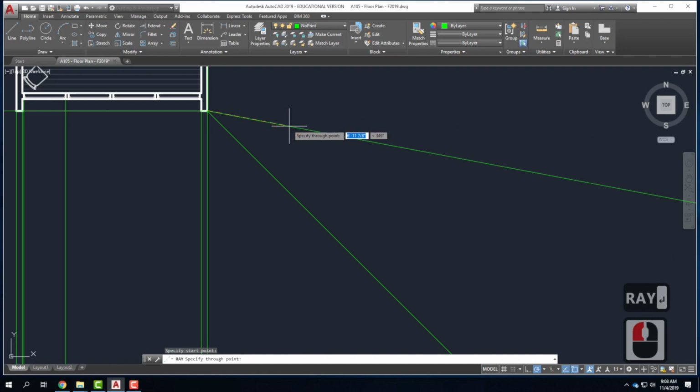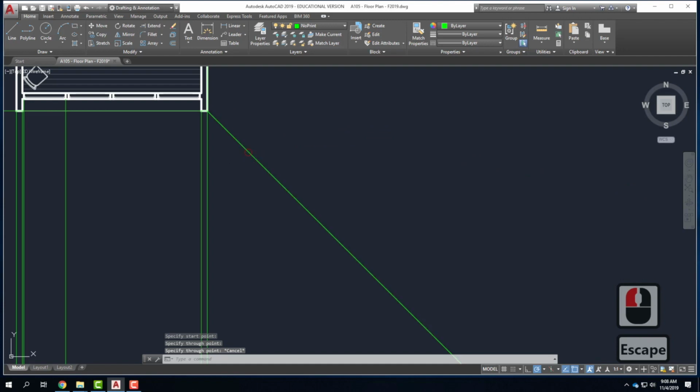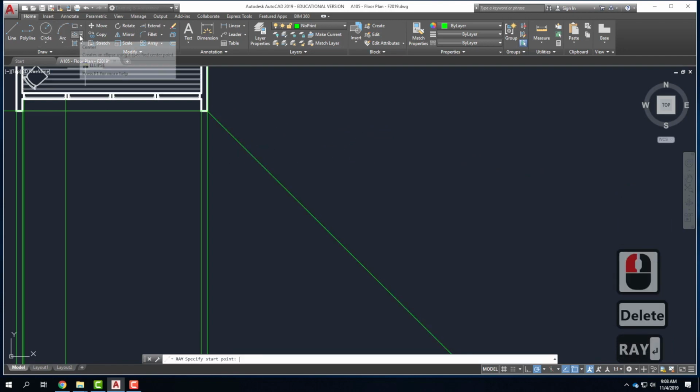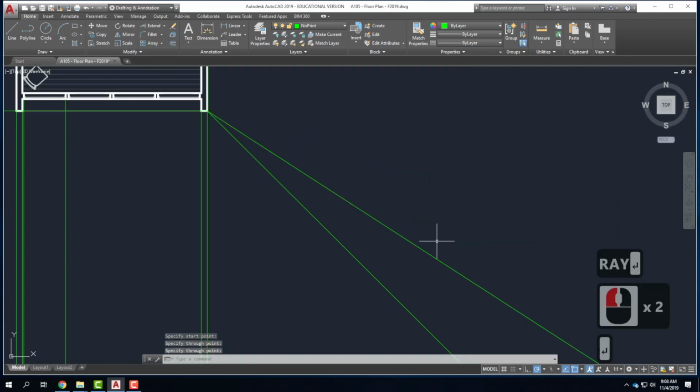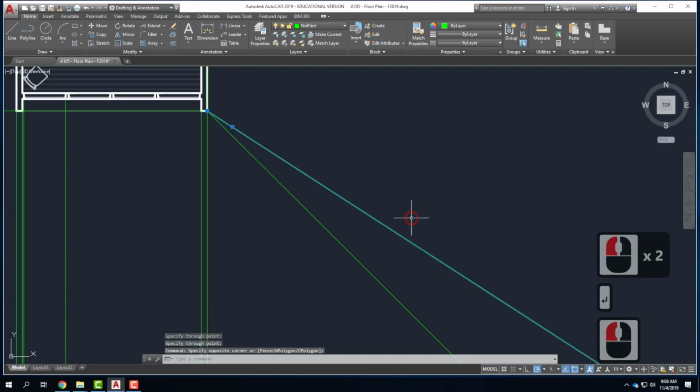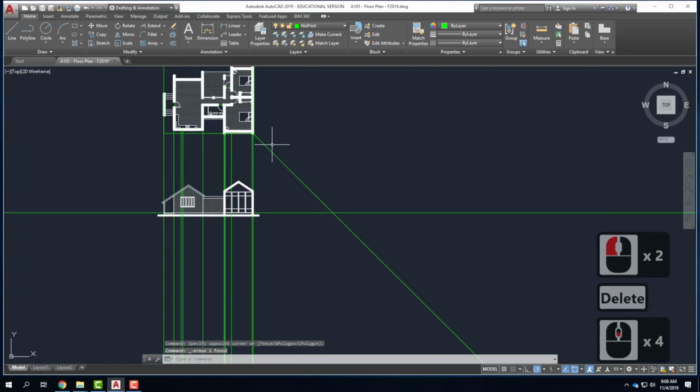So I'll go ahead and type tab, and I'll type negative 45, and then tab again. Yep, it's right on, and then a single click. So I ended up with 2 of them. You don't want to end up with one that's off, like that, because it won't pass your measurements through as easily. Okay, so I have that line from the 45.